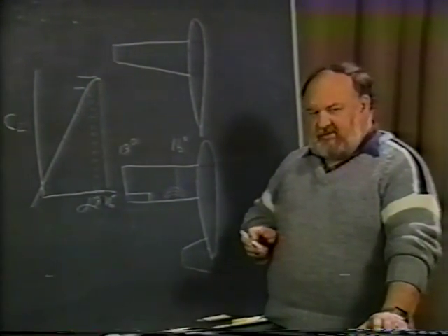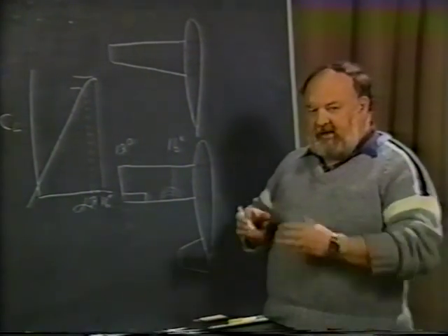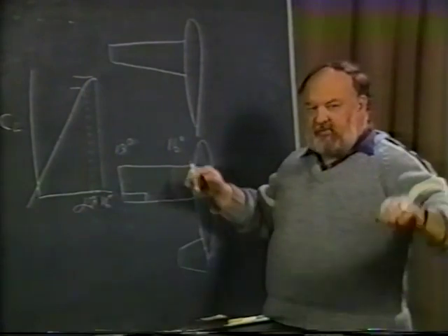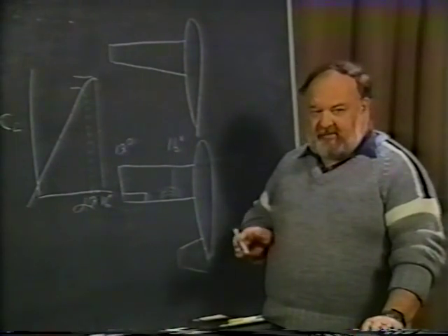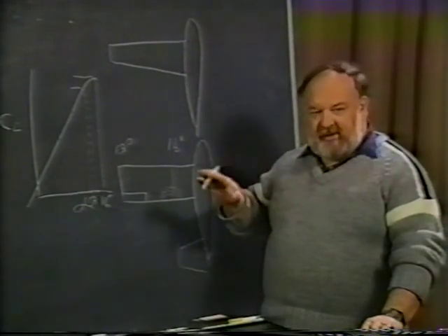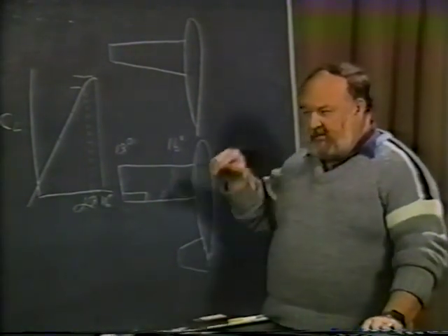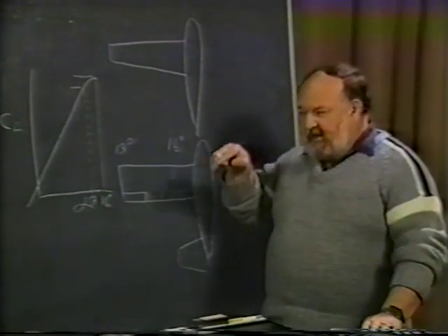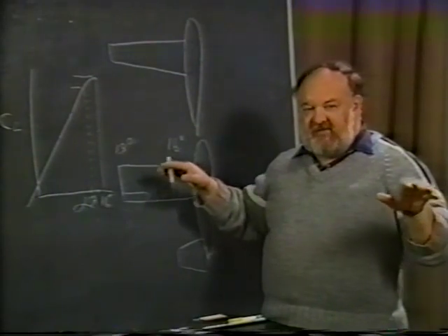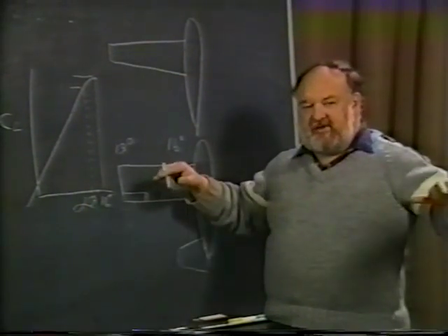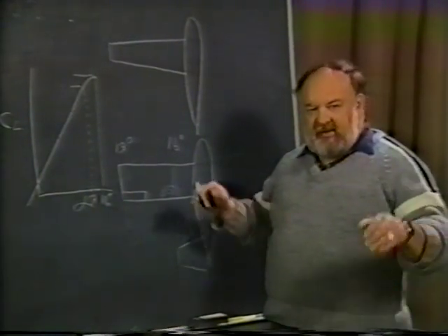About 10, 15 years ago, there was a high-performance sailplane where the designers built a little bit of washout into the wing. Now, here you are with a long aspect ratio wing, and they put this washout in it. Why, I'm not sure. I guess they really wanted a nice stall characteristic for a sailplane, but that's not really important, because you don't bring a sailplane in that landed at maximum CL. But in any event, after a competition one time, he came racing across the finish line, trying to get there as fast as he can. And as he dove through the finish line and pulled up, the outboard sections of the wings literally structurally failed downward, because the outboard section of the wing was flying at such a negative angle of attack at that high speed that it overloaded the wing spar in a downward direction.